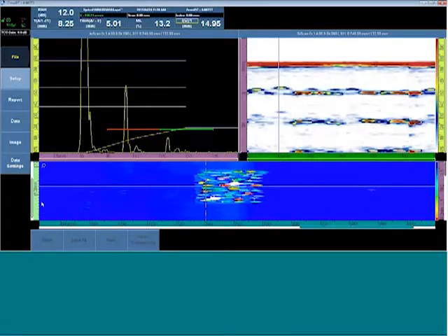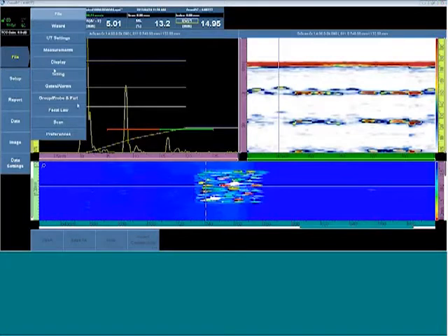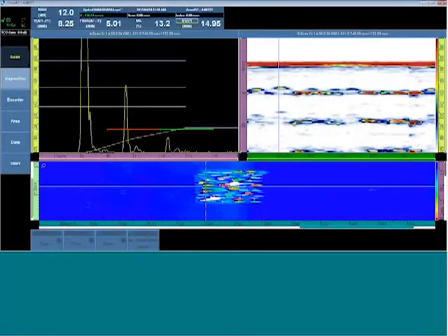So this C-scan was built with multiple strokes, we would call it, and each stroke represents a 50 millimeter line. So if we look at the scan menu, in this inspection, we've selected raster scan, and now we have to assign encoder 1 and 2 to the scan and index axes. So instead of just having one encoder, now we would have two, and they would both be configured independently with a resolution and an origin position.